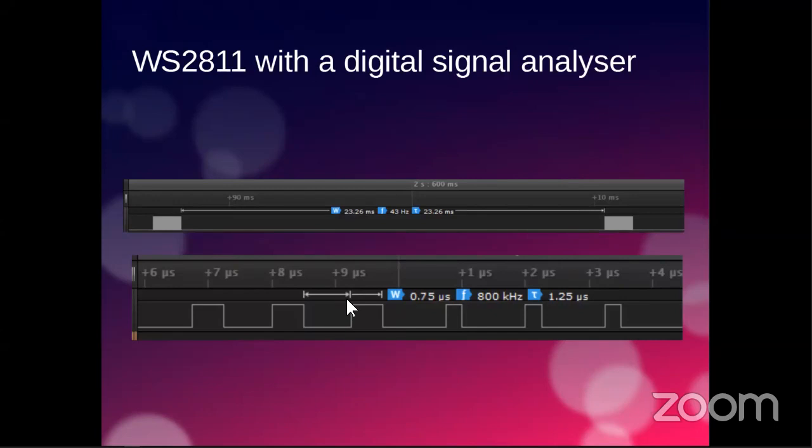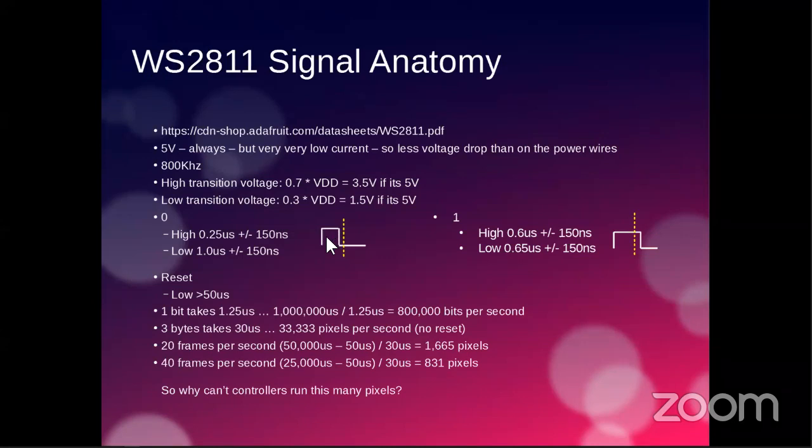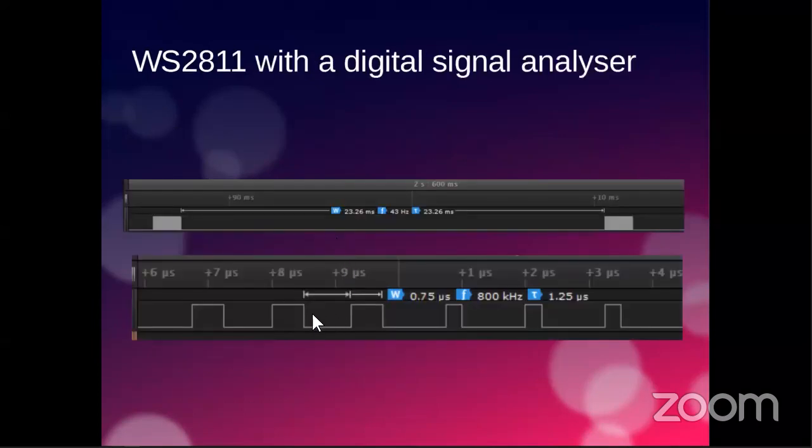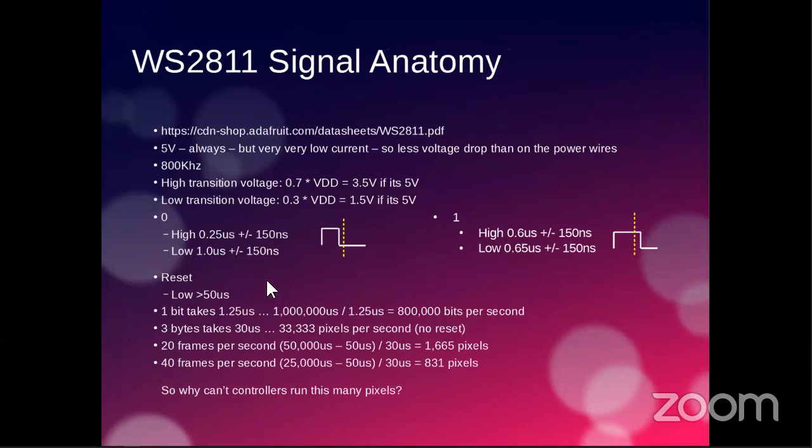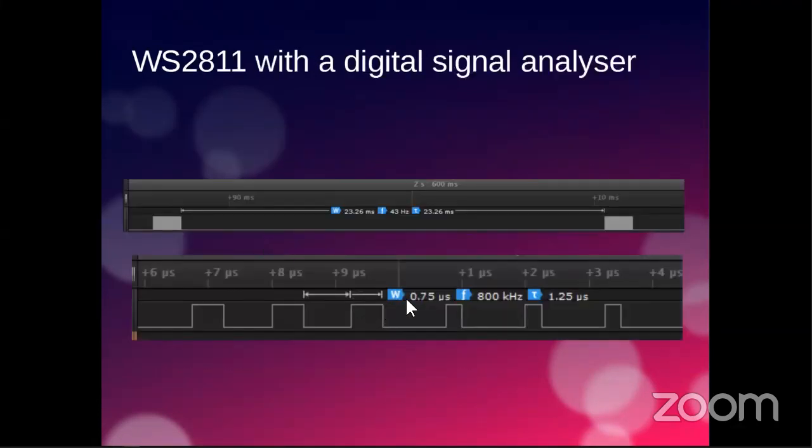You can see the signal timings. Dave doesn't use, strictly speaking, the standards. Dave has found that if you run the high a little bit long, you generally get better compatibility across a broader range of pixels. And so he runs 7.75 microseconds, which is right at the end of the threshold here. This is the error factor on what the signal's allowed to be.